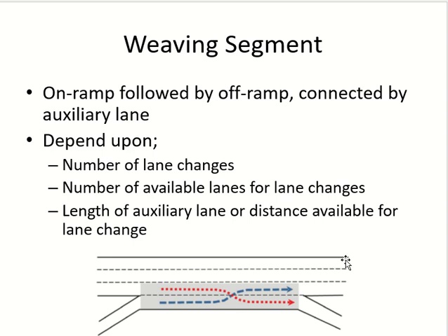And how many lane changes people are forced to make because of your lanes? So number of lane changes required because people want to go from the freeway to the ramp or ramp to the freeway. This is required by them. And how many lane changes you are forcing because of the design. So this will affect the traffic flow.